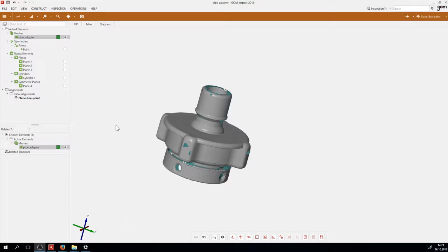So next thing that I'm going to show you is mesh editing. There are many changes that we can do to this mesh, and first we have to open the correct menu. You have several, so 4 different menus here. Right now we're on inspection, but what we need to be on is mesh editing. And now here we have a few different things.